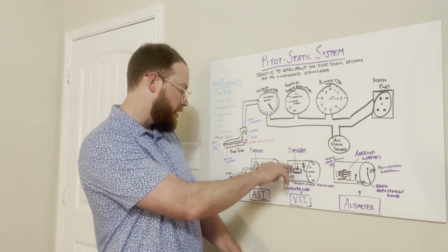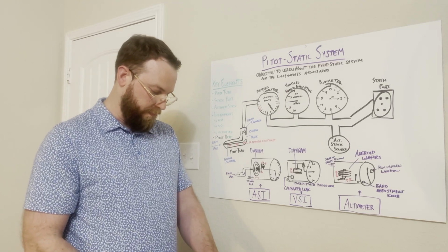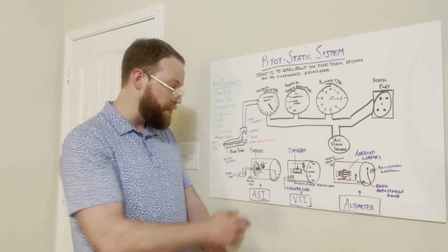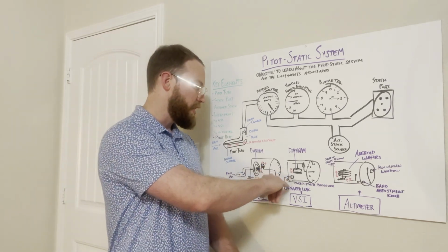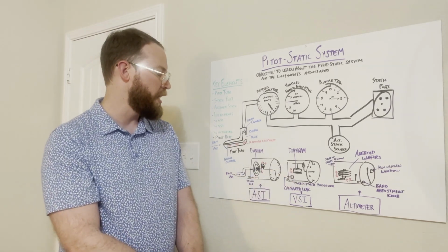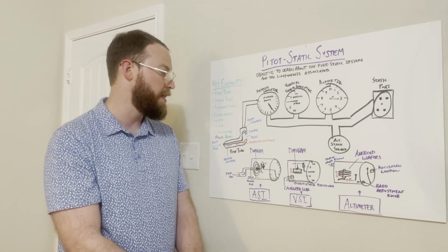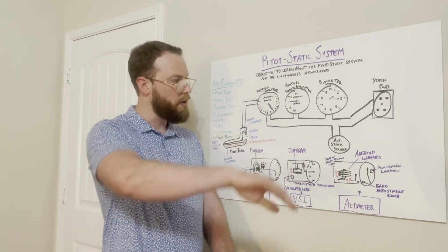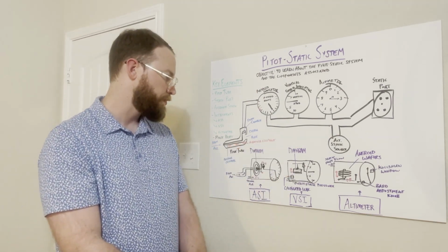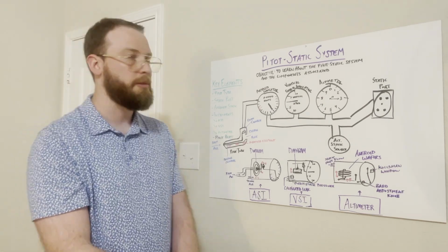So both the diaphragm and the static pressure line receive information, and typically with the VSI there's a slight lag or delay from the difference between the static pressure and the calibrated leak. It typically takes a couple of seconds, 2 or 3 seconds, to settle and give that accurate reading. Some errors come with that, which we're going to get to at the end, but there are some errors that come with all 3 of these instruments that we'll talk about shortly.